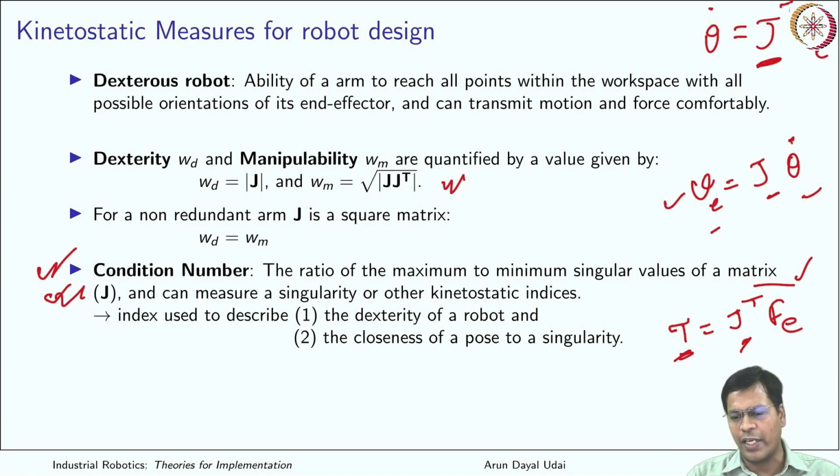If it is close to singularity you cannot do this, and your robot gets stuck. If you are using any control algorithms, they definitely use this and your robot gets stuck. That is known as a mathematical singularity.